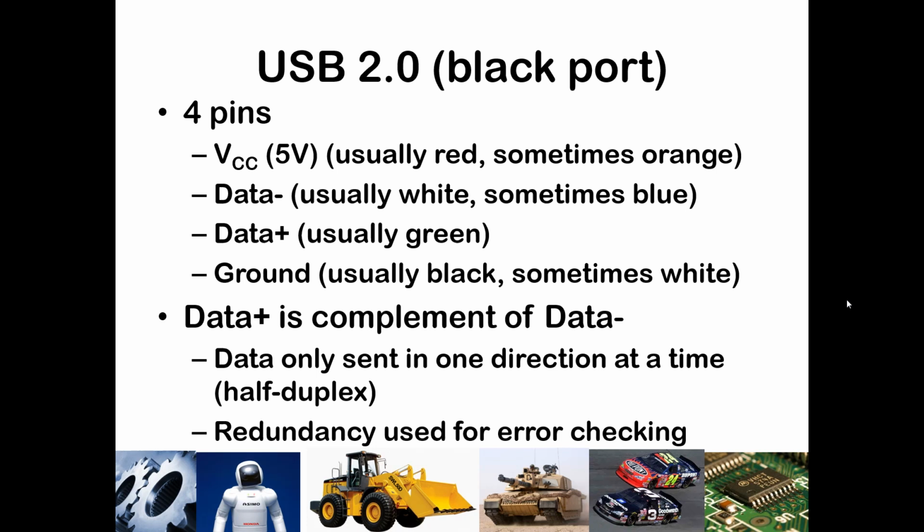They have 2 data pins. One is data minus, the other is data plus, and you can see on the slide screen the colors of these wires. If you were to ever cut open a USB cable, you would typically see your 5 volt signal is red, your ground is black, and your data are white and green. Sometimes the data minus is blue, depending upon who's manufacturing your USB cable.